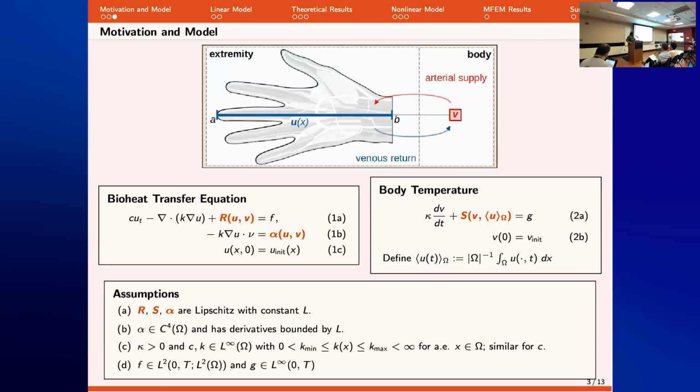Also, for the boundary condition, we're going to use for these results a simple linear Robin boundary condition modeling heat exchange with the environment. But I could imagine a world where someone might want to use a more complicated boundary condition, like a radiation boundary condition that is itself nonlinear. And so we are going to show theoretical results that account for a potential nonlinear boundary condition as well.